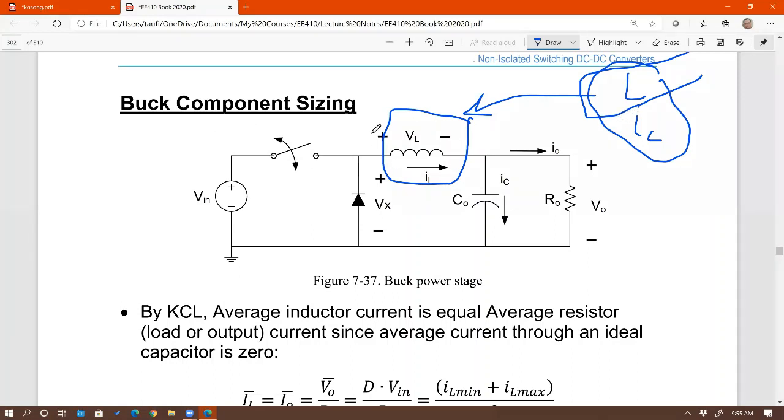Why? Because in power electronics, we deal with higher currents, so you definitely don't want to ignore the IL peak. What if the current exceeds the IL peak rating of this inductor? What's going to happen with that inductor? If it's more than just a transient, you're going to overheat the inductor or possibly damage it.